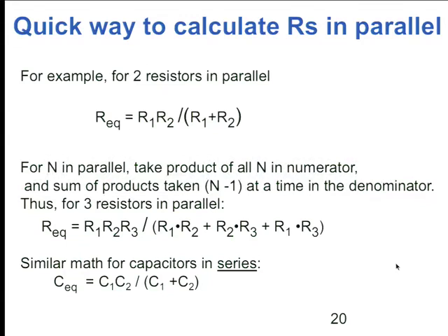Suppose we do the product. A half of 1,000 times 1,000 is like a half. Divide by the sum. 1,000 plus a half 1,000. So if the product is a half and the sum is 1.5, so the resistance here should be 1/3, right? 1/3 of 1,000 ohms, about 300 ohms. That I can do in my head. You follow that? Okay. So that's about 300 ohms.